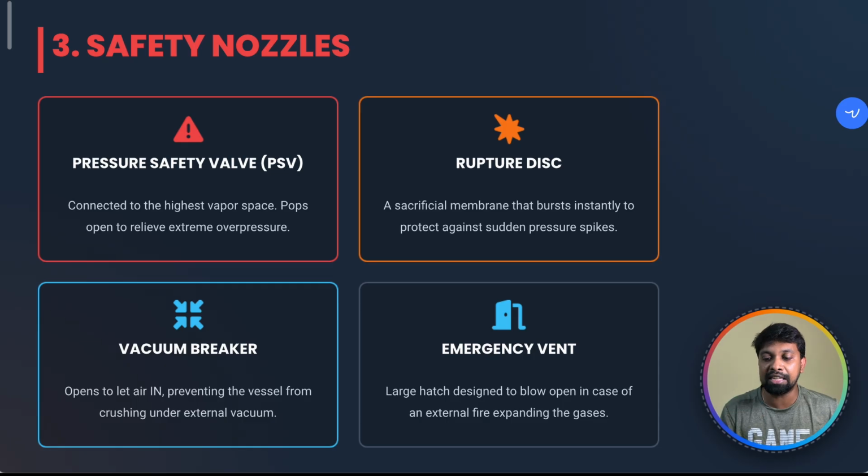If the pressure vessel fails, then the rupture disc will do this work. It will break a small membrane and release the pressure. It will cause permanent damage to the rupture disc, but it will save the whole vessel. So we use the rupture disc.